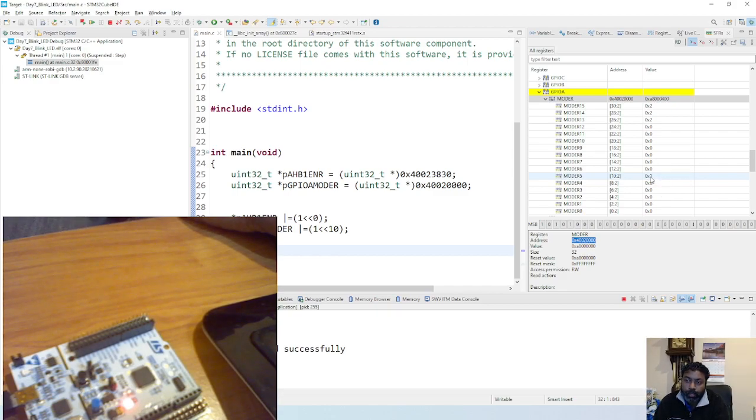So this is what I did earlier. I enabled this manually, but now you have written this code and you're also verifying that through SFR, which is equally important. So if you are in doubt, go to SFR and then see for yourself whether your code that you meant to write is happening. Check bit by bit and register by register.